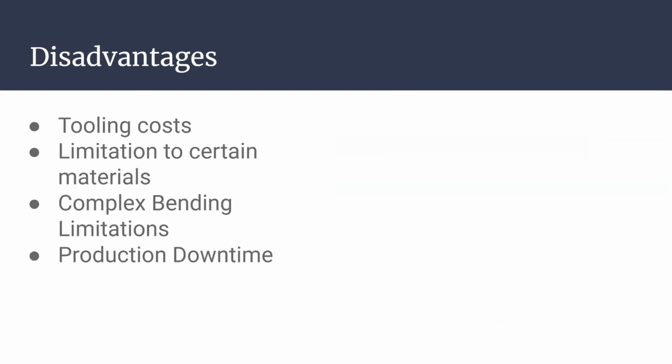One disadvantage is the tooling cost. Developing custom roll forming tooling can be expensive, which may make the process less feasible for short production runs or prototypes. Roll forming is best suited for thin to medium gauge materials.